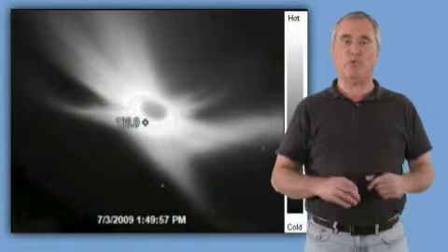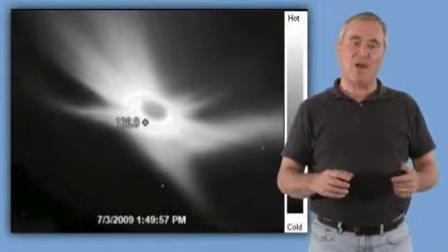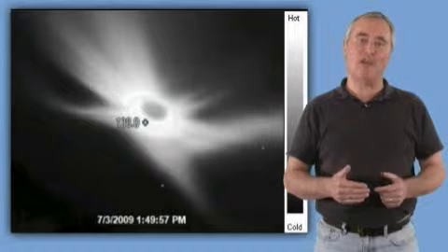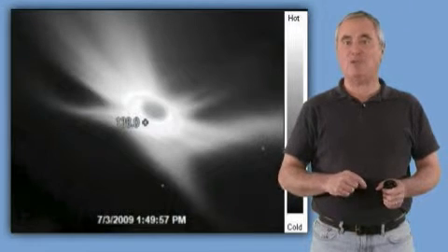If we hadn't reversed this leak, we wouldn't see much at the recessed light fixture. But as we accentuate it with the blower door, exerting about 20 times more pressure than the building typically sees, then we can see these leaks quite easily.